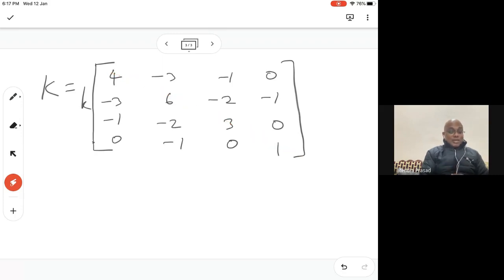You will also notice here you can cross check, especially in case of a spring system with two noded elements, and in fact in all structural systems where forces and displacements are related, you can add all the rows or columns and that will be equal to 0.